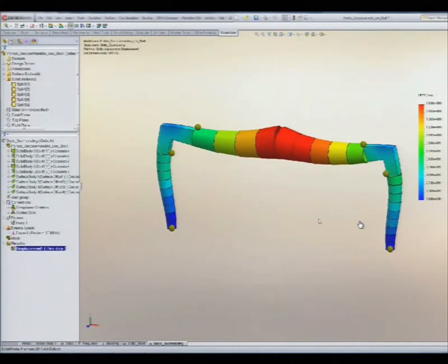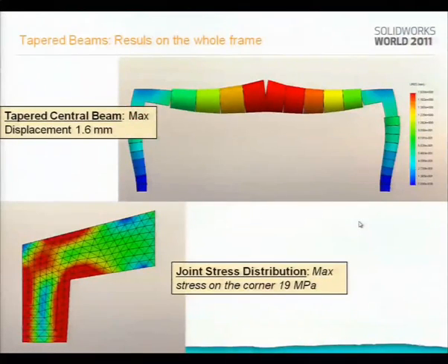And this is the result. You see, the solid elements follow the beam element, right? So this is the submodeling technique. For this load and with this technique, I got the result on the beam element, on the frame, 1.6 millimeter, and on the joint. It's very useful for civil engineers that work with reinforced concrete. This is von Mises, which, as I told you, is rubbish.